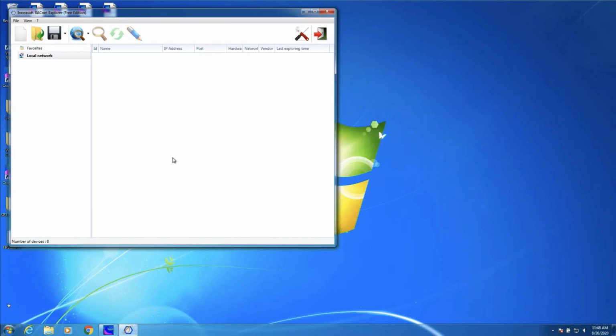One of the benefits of BACnet is that you have the ability to explore the network, and a tool like this can effectively, without really knowing anything about the BACnet server out there on the network or a whole series of servers, can explore the network and pretty much discover all that information in terms of what objects are supported, what they're named, all those sorts of things.